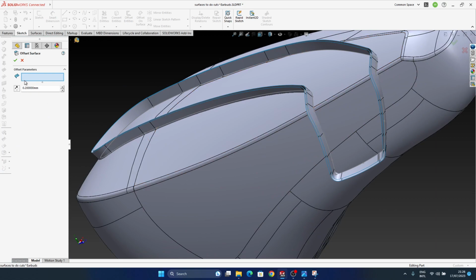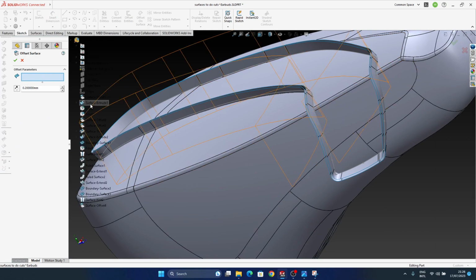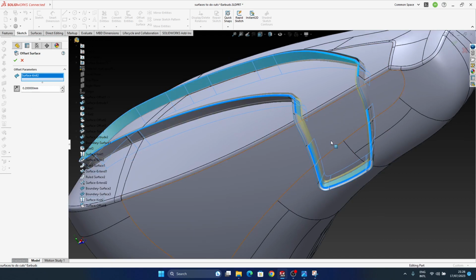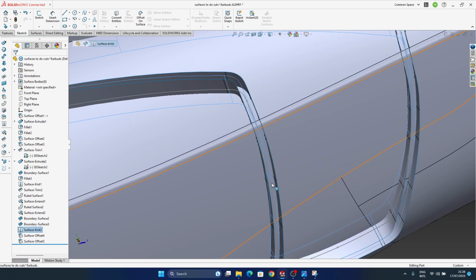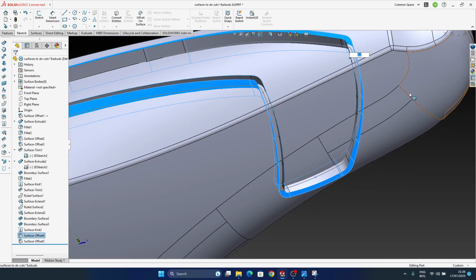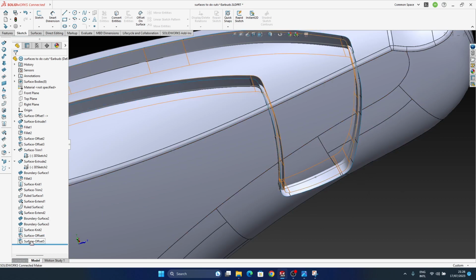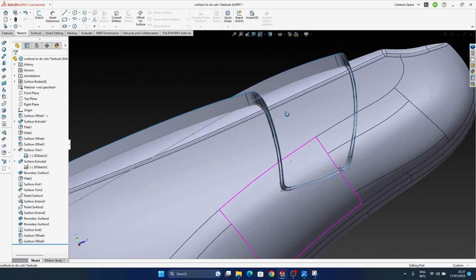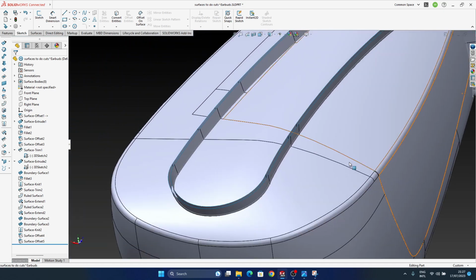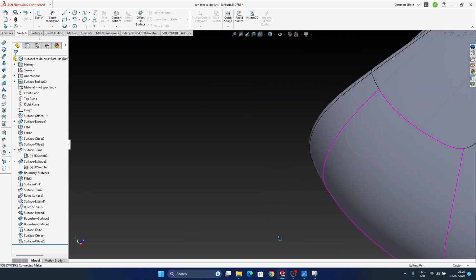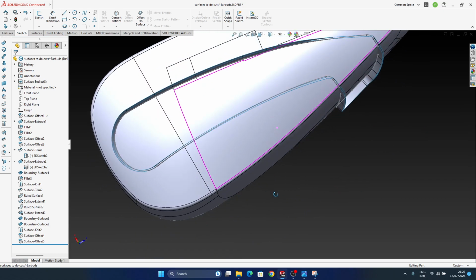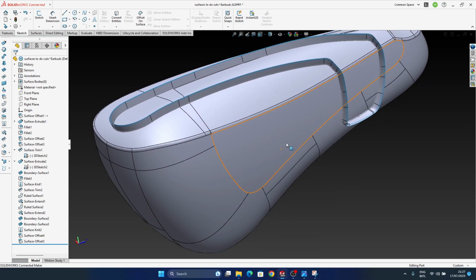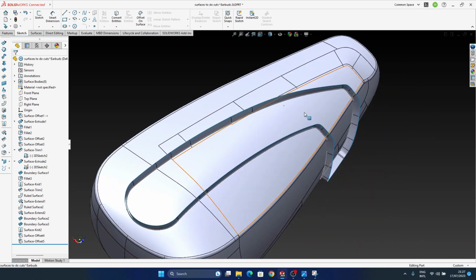SolidWorks. Okay. So offset from this, but on the other side. Okay. So now we have the offset of 0.2. Okay, so 0.2 definitely is not the right thing. I will put it at 0.1 and as well this offset at 0.1. Okay, so now that means that we have created the first surfaces that we can have in here to just cut. Just checking the time, almost 1 hour, so we are near the end.